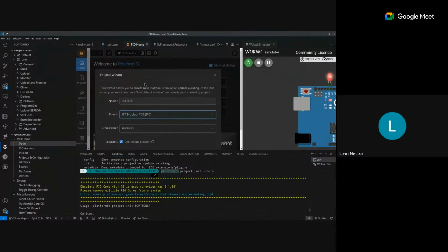If you are using any board, any framework, these are the frameworks that are available here. Arduino framework is the setup and loop based framework, and you have STM32Cube framework, which will be using STM HAL. You have seen STM HAL, right? And these are the other frameworks that people use. For STM boards, we use this framework. You can also use Arduino for STM32, but STM32Cube cannot be used for other boards. That is specific to STM32 only. But Arduino can also be used for this. And these are different HALs, hardware abstraction layers and frameworks that people use.